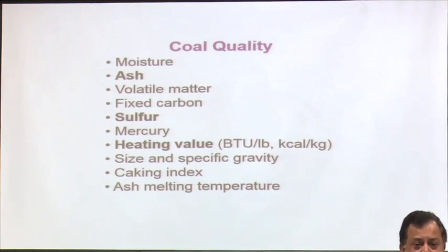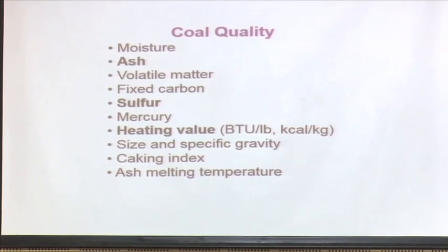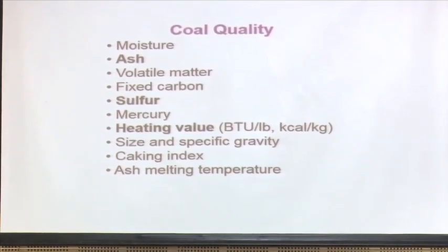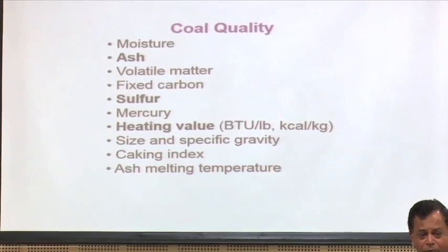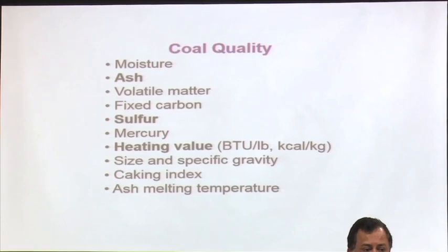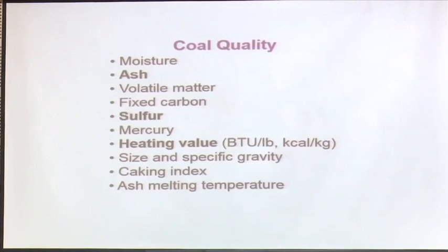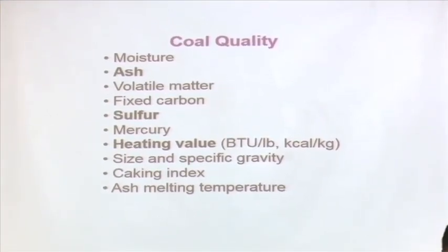So, it plays a dual role, but there I cannot charge coal because blast furnaces normally have a minimum height of around 100 feet and the raw materials are fed from the top. So, the raw material for a blast furnace is basically the hematitic ore Fe2O3, and I need to take out my oxygen. So, I need a reductant.